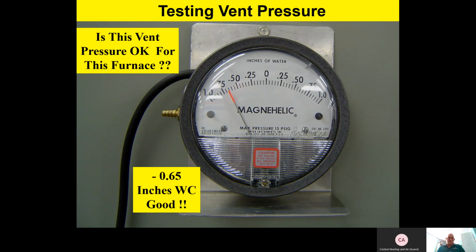Now that's just a general field observation. So if it closes at 0.5, if the vent system's in good shape, a 0.75 or 0.8, something like that would be about a normal vent pressure.